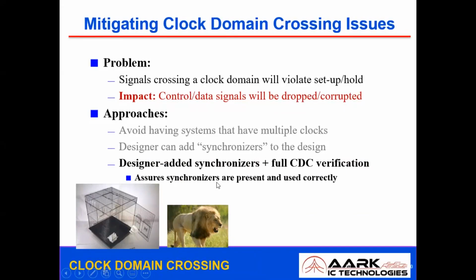We have discussed adding synchronizers, and synchronizers might create additional problems, but those problems can be rectified. Reconvergence errors can further be rectified by adding additional circuitry, for example through gray code or FSMs. This makes sure that the metastability, or mean time between failures, is improved. We are not completely avoiding it, but the reconvergence problem can be rectified by adding additional logic circuitry through FSM controls. That will make sure that you have a predictable nature. With this, we are adding predictability to an unpredictable behavior.